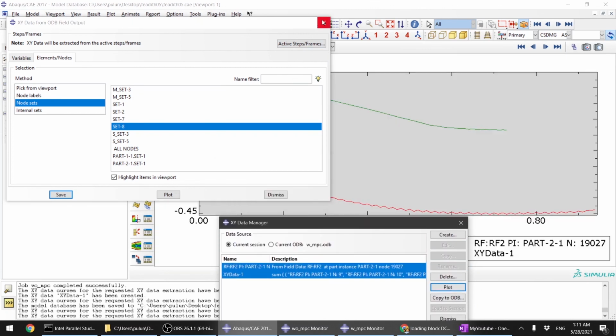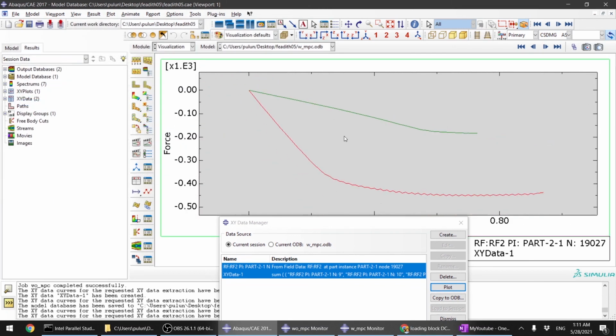See? Yeah. So it's a totally different curve, different stiffness, because we performed a wrong simulation here because we didn't assign a correct boundary condition. So it's really important, guys, to assign correctly the boundary condition when you're doing DCB simulation or any simulations.